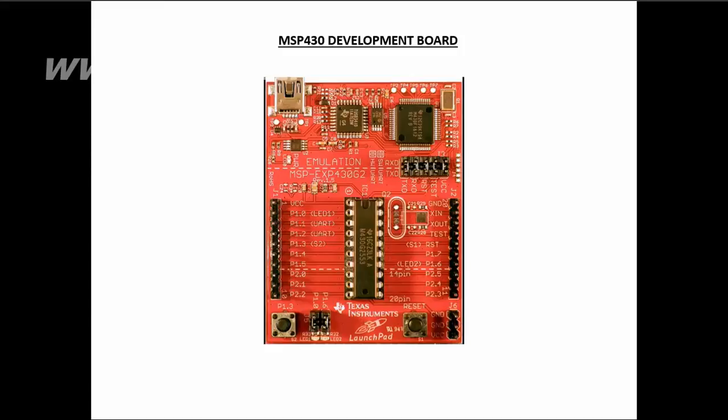Let me give a brief background about the data bus and the control bus, assuming that you already know the background of data and control buses. Both the address and data buses here are 16 bits wide. The registers in the CPU are also 16 bits wide and can be used interchangeably for either data or addresses.